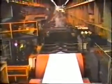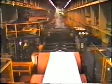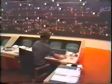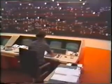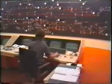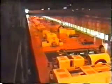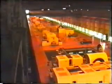Unfortunately, this perfect, steady-state condition rarely lasts for more than a few seconds because the customer load demand is always changing. But these changes in load are relatively small, and moreover, they are usually anticipated according to the time of day and weather conditions. As a result, there is normally sufficient generating capacity online, and with the help of automatic equipment such as turbine governors and voltage regulators, the power supply can be quickly adjusted to meet the load demand.